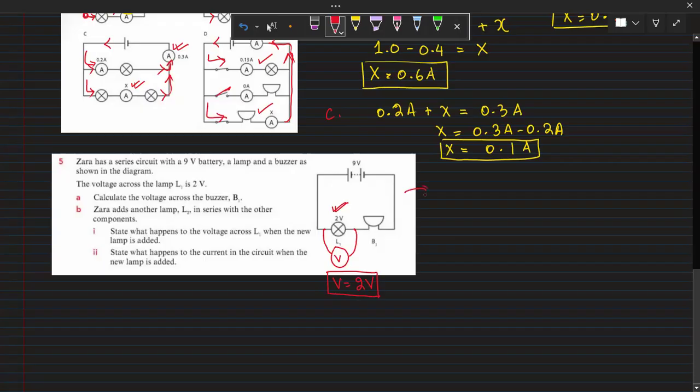What I know is that since it is a series circuit, one after another, the current has only one path to flow. So current remains the same. The total current will remain the same. That means whatever the total current is in the circuit will have to flow through each component equally. The next thing is what divides in the series circuit? Voltage divides, across the components. Clear?